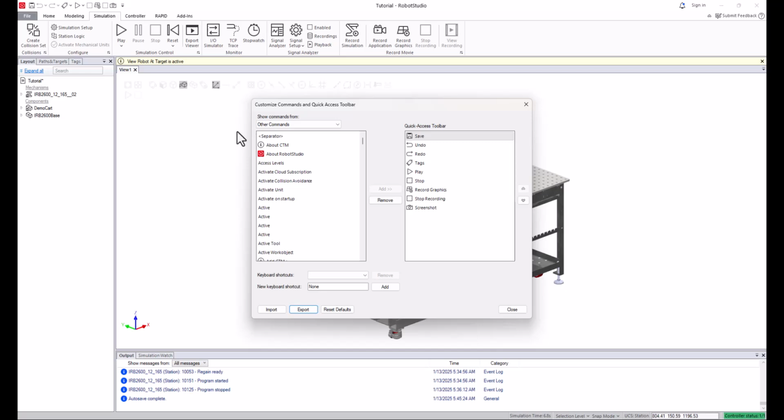I spent a little bit of time talking about this because I think that this is one of the most important things that you can do, that you get really good at being able to use keyboard shortcuts to be able to do all kinds of different commands in RobotStudio and even in the Rapid editor, right? So if I come down into Rapid, there's a whole bunch of commands inside here that I think are super important, like commenting and uncommenting. Control-Shift-E, Control-Shift-W. Use that all the time to be able to comment out a block of code. Super quick, super easy. I already went over the apply. My apply is, by default, Control-Shift-S, so they don't actually allow you to change it there. That's going to always be there. Yeah, so really important to be able to do that.